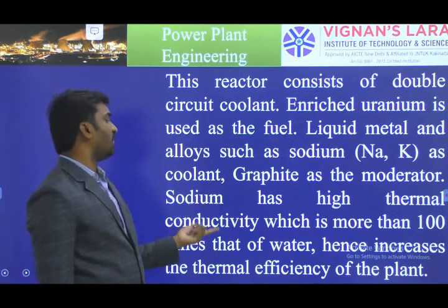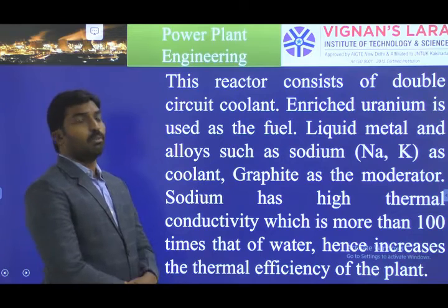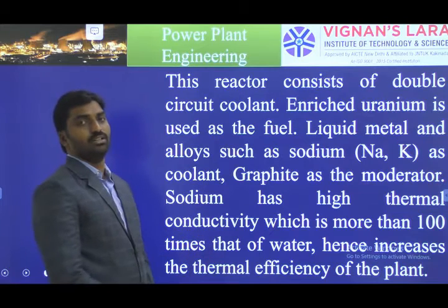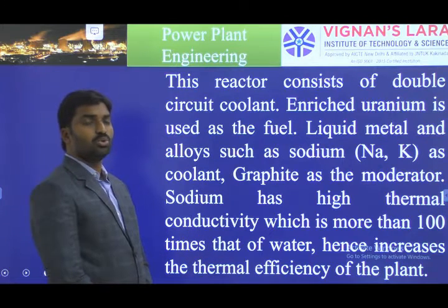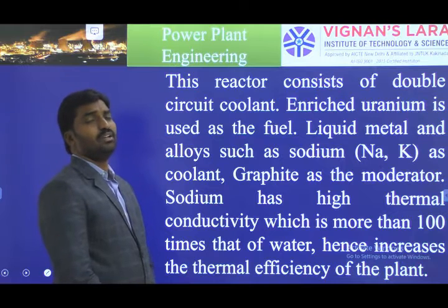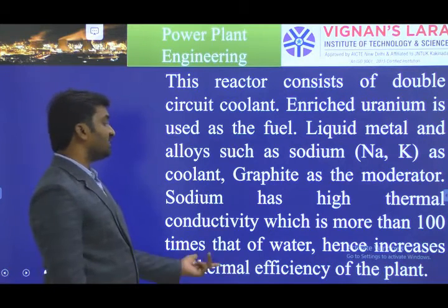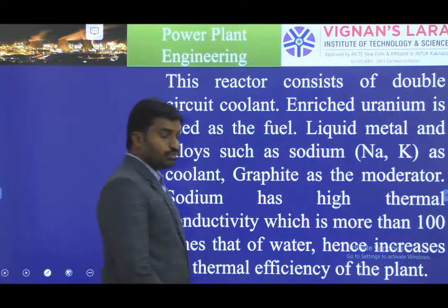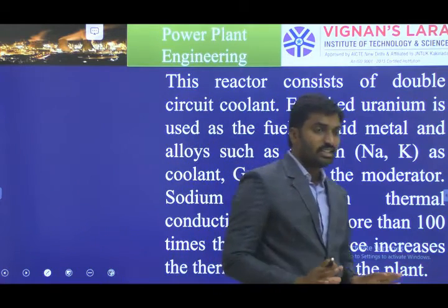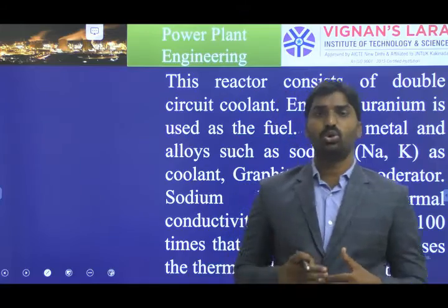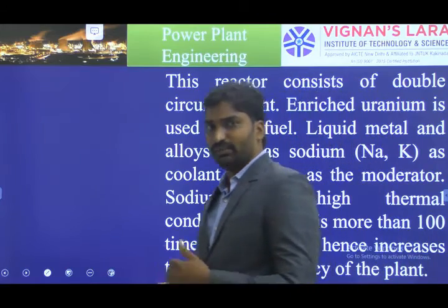Sodium has a high thermal conductivity, which is more than 100 times that of water. That's why we are using sodium as the material here, for better thermal conductivity values, hence increasing the thermal efficiency of the plant. When we use a high thermal conductivity material, automatically it shows its effect on the thermal efficiency.